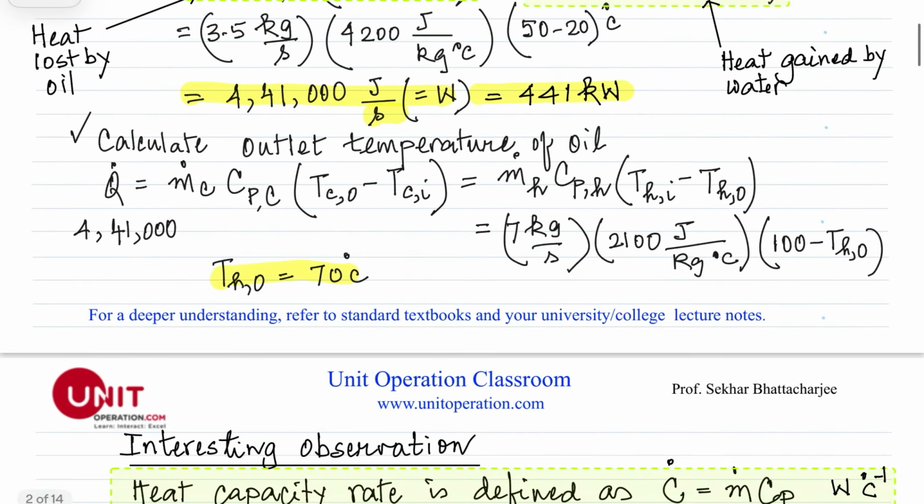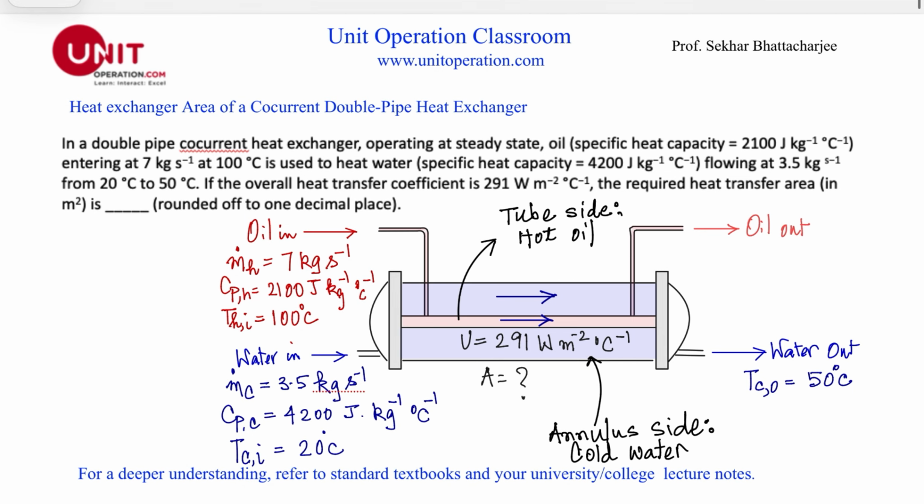As the hot stearic acid comes in and is cooled down, in the countercurrent one the coldest water is coming in. Since this is now cold, it tries to solidify the stearic acid, which leads to deposition and other problems.